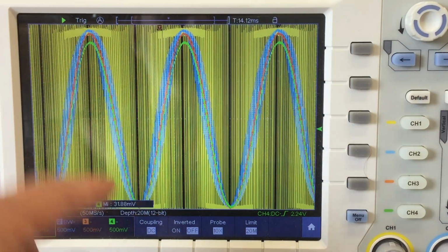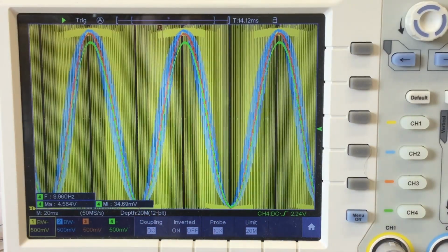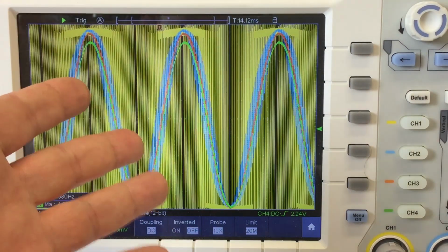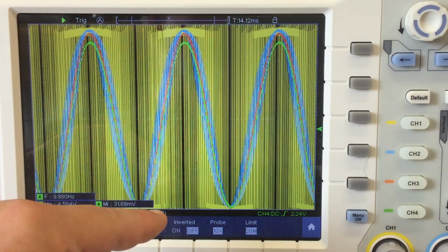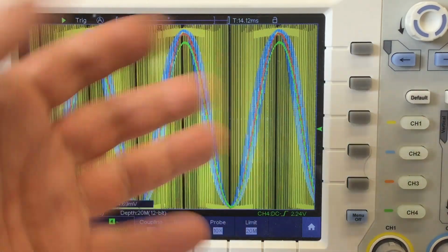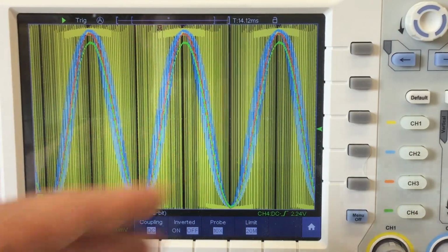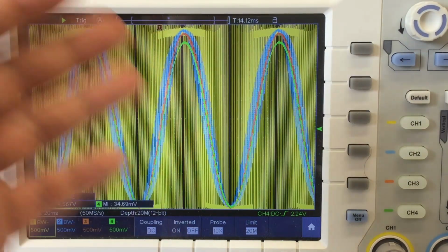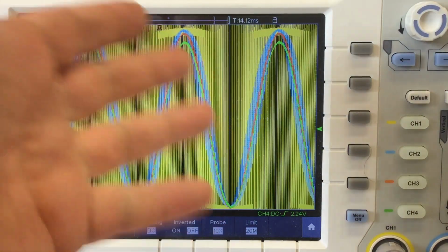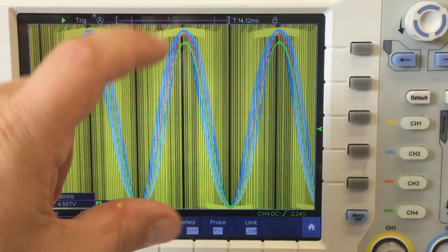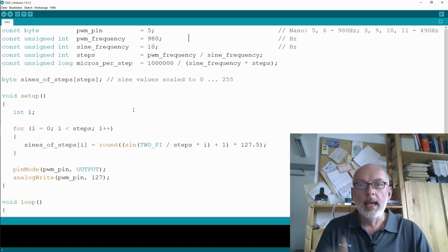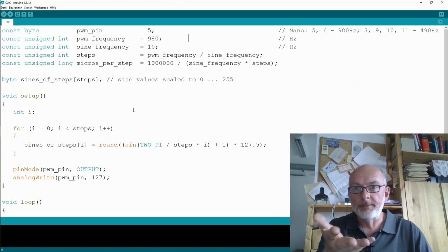And basically, if you want really precision on your amplitude, this whole approach is not for you, because the 5-volt rail, which should be on top here, is not really stabilized. It has absolutely no precision. If you are lucky, the rail will give you plus minus 5%, minus the real world dampening you're experiencing here. Yeah, so absolutely no precision on the amplitude. Okay, enough of that analog stuff. Let's have a look at the code.